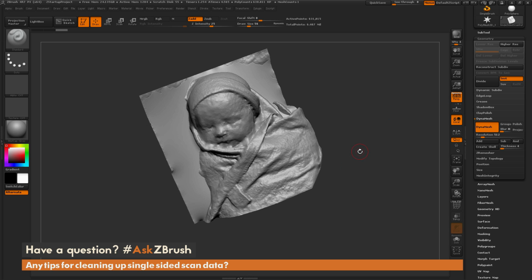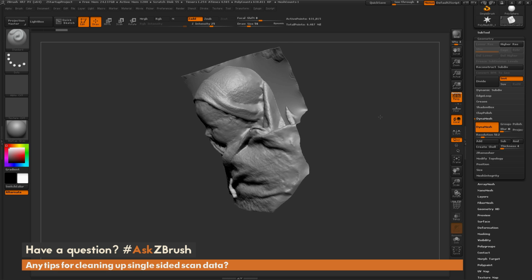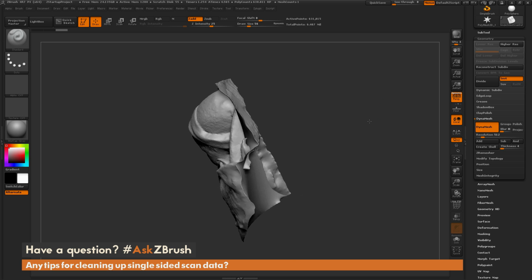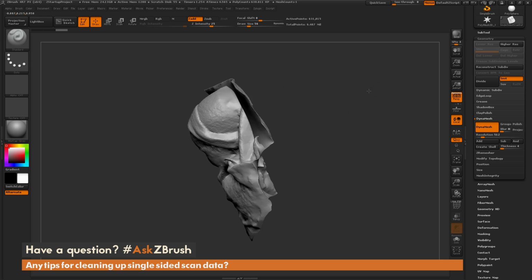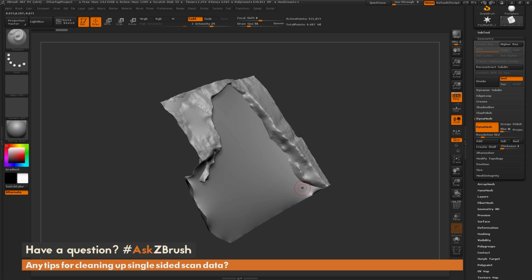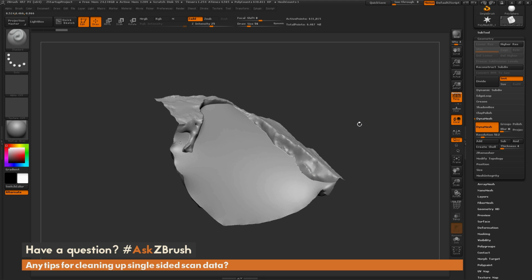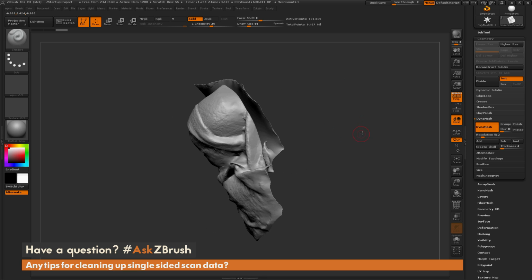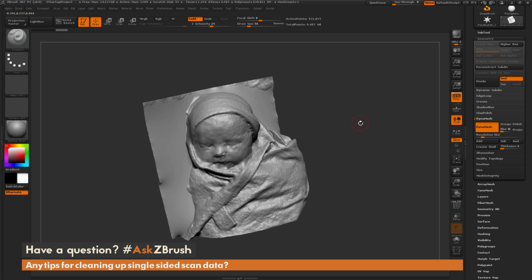Now, if you're lucky, sometimes this will just give you a perfect mesh right out of the gate. So you can see the DynaMesh went through and closed some holes, and it did give me even topology everywhere. However, the scan data, being as rough as it is, has generated a lot of issues. So you can see I have a lot of thin areas on the model here, starting to get some of that DynaMesh Swiss cheese. And you can see the back is a total mess. So I have a lot of interpenetrating geometry now, and it's just made a big mess of the model here.